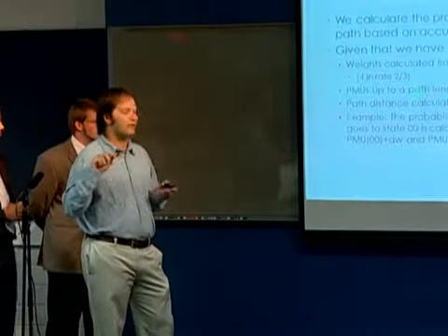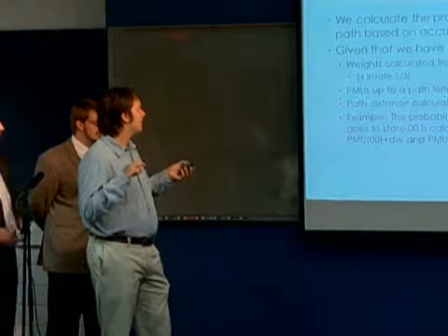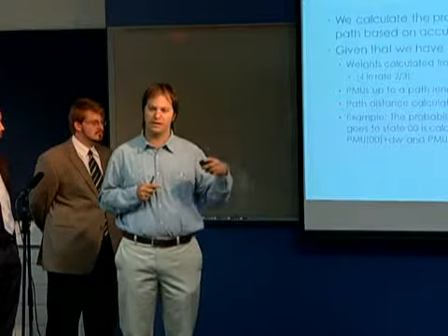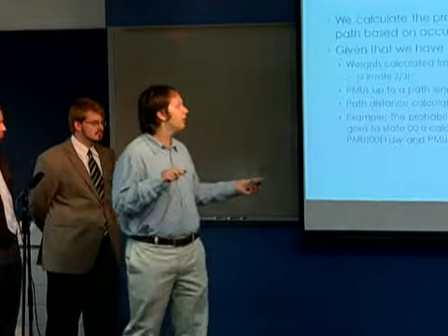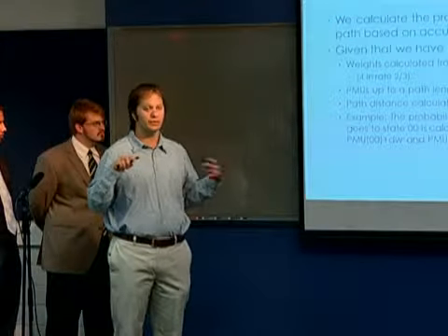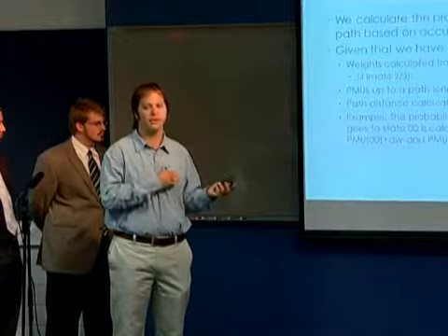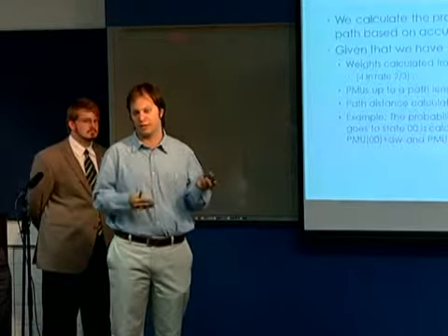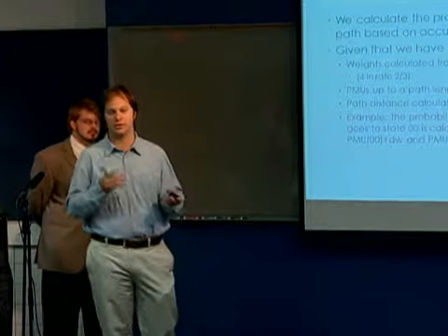So we take whatever number of states we have, and for each of these states, there are 2 previous possible states. For example, state 00 could have come from state 00 or state 10, so state 0 or state 2, when the choices are state 0, 1, 2, or 3.